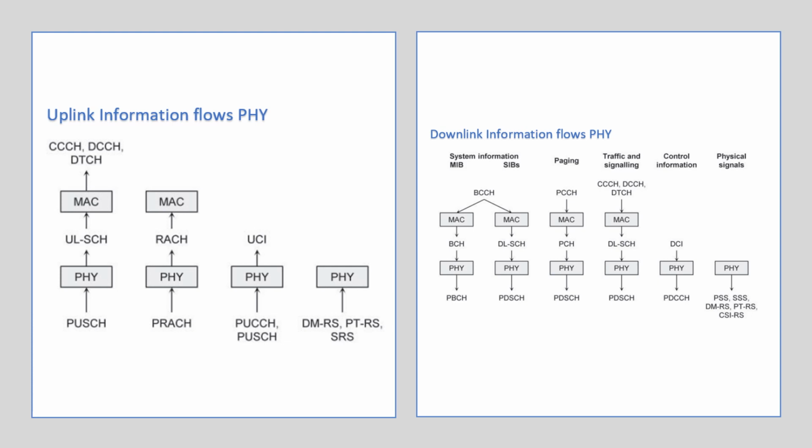Now, on the uplink, the sounding reference signal, that is SRS, helps the base station to estimate the best choice of uplink subcarriers as well as the best modulation scheme, coding rate, and antenna configuration. On the downlink, that role is filled by the channel state information reference signal, that is the CSI-RS. So there is no equivalent to the downlink cell-specific reference signal from LTE. Instead, their role is handled by CSI-RS and DMRS.